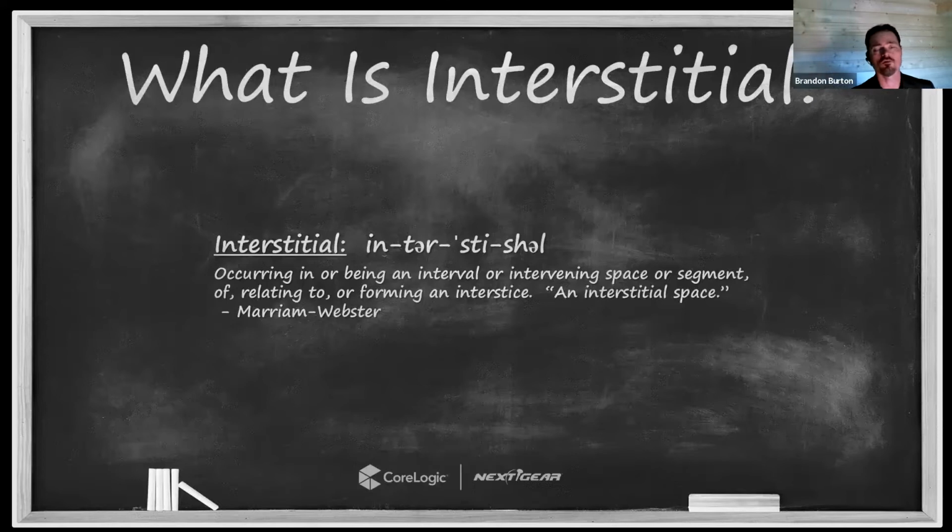Right? If I put a dehumidifier in that space and start controlling humidity, I am not going to directly control the humidity in these interstitial spaces, not unless I do something in addition to ensure that the effect of those mechanical systems is being imparted onto those interstitial spaces.